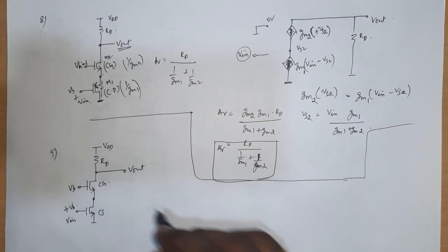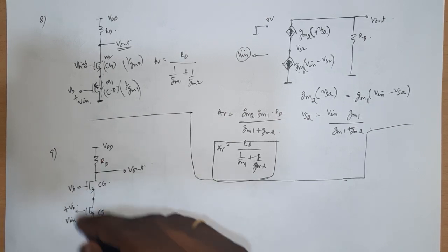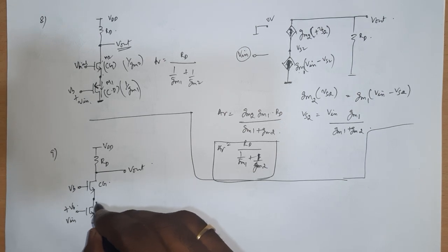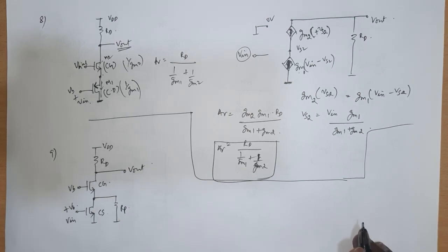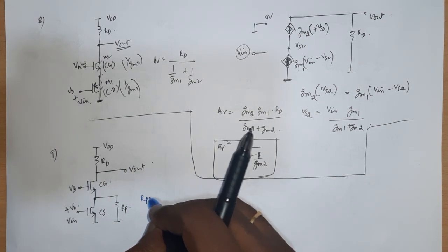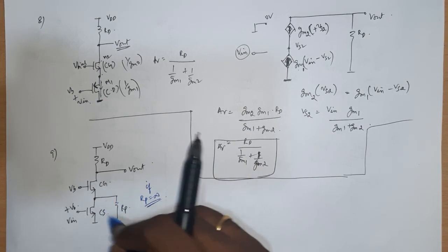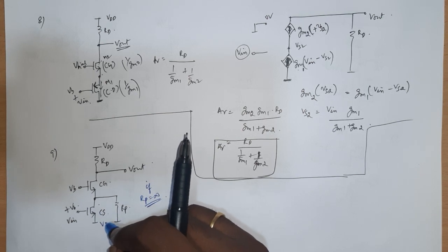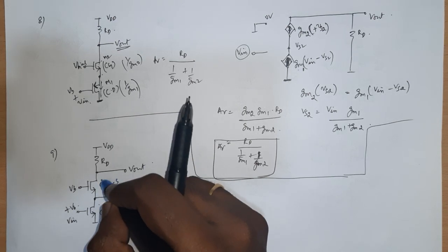Okay, so now if this is the case, we have done this earlier, when we illustrated the cascode amplifiers, but then let me pose a new situation: say I have one more resistor RP here. So when RP is infinity, that is, when RP is absent, we said that this is a common source amplifier, which is a voltage controlled current source, and this is a current controlled current source. This just passes the same current, right?